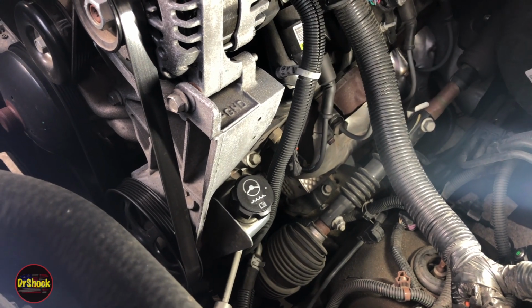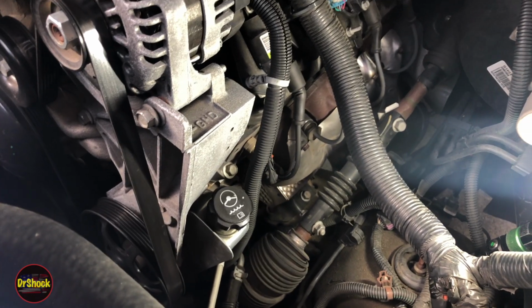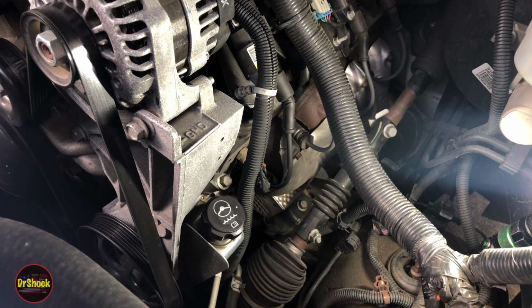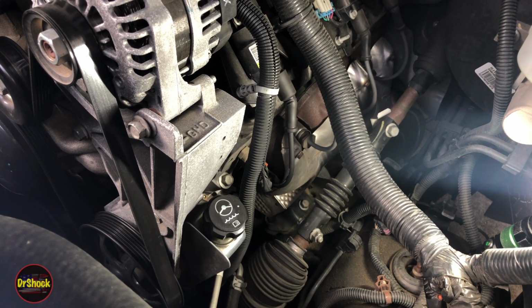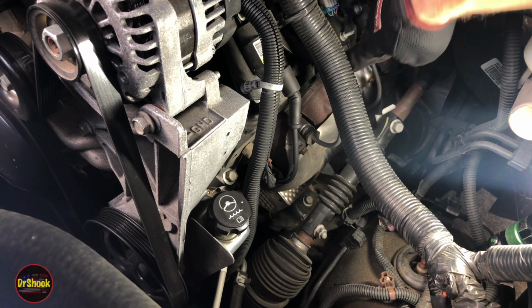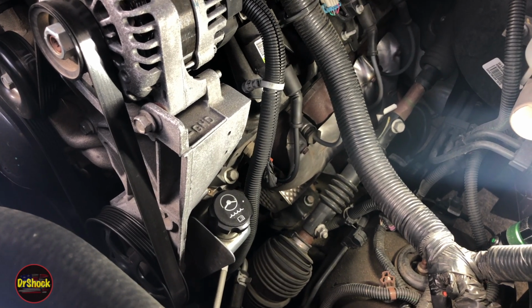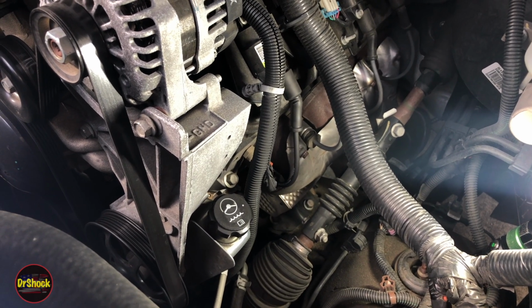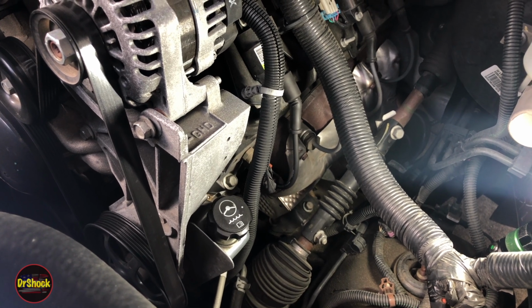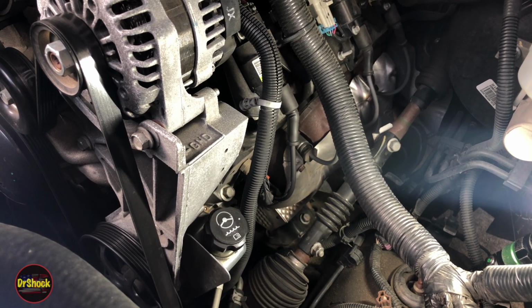Like a double click out of that one. All right, so that's how we're going to do all of these. I'm going to go ahead and replace all of these because I just measured the number 3, and it also is not in specification, the number 3 ignition wire. So we're going to replace all these ignition wires so they're up into specification, and then we're going to continue pulling each of these plugs to see which ones have been affected from the oil burning.